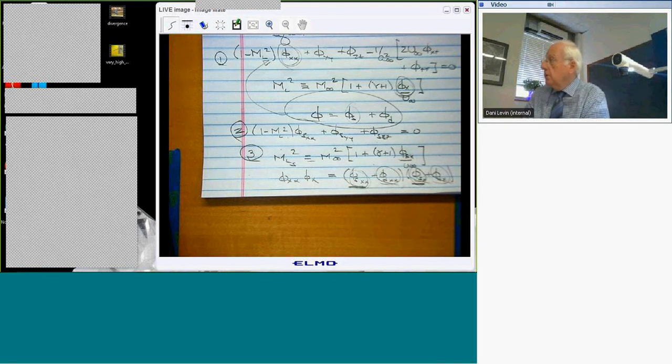So even if you're running the CFD code, what you might do is compute the steady flow, Euler or Navier-Stokes, and then give it a small perturbation, small motion, such that you're fairly certain that the answer is linear in the motion. That is, the unsteady flow field is proportional to the amplitude of motion. In fact, you could try different amplitudes of motion and see how far out you can go, and everything remains linear in the motion.